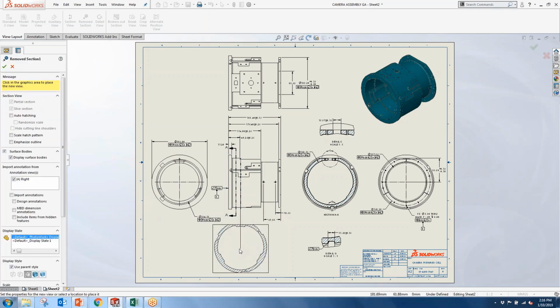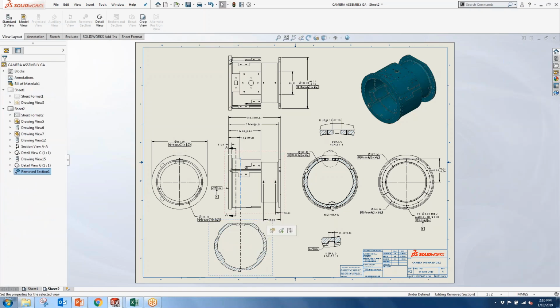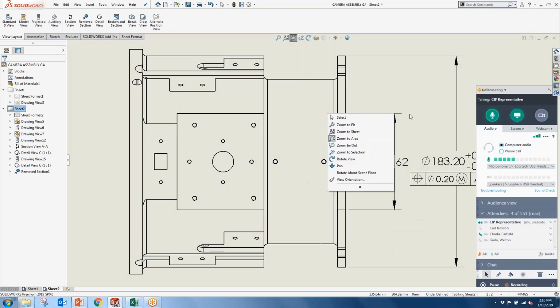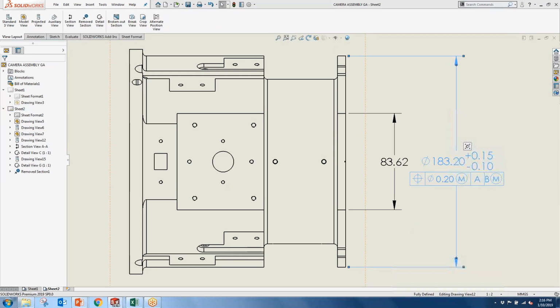So you can get some pretty unique orientations as need be, but I'm going to just drop it right here, and then it creates our section view, our sliced section view, directly perpendicular down or up to our cut line. So this allows us to create slice views very quickly. And again, with that being able to lock it in between the 2 edges, you could get, like I said, an advanced method of getting unique cuts.